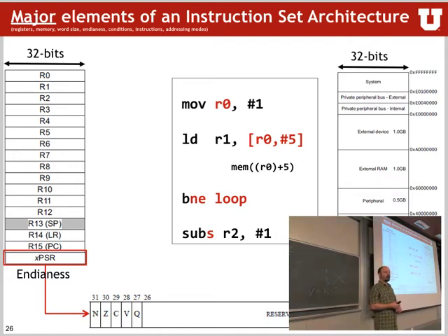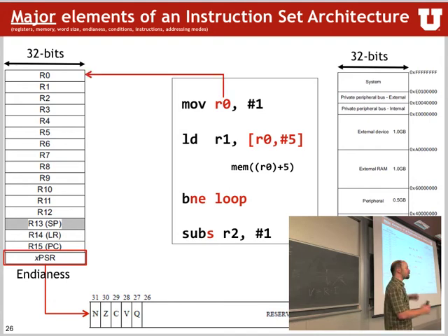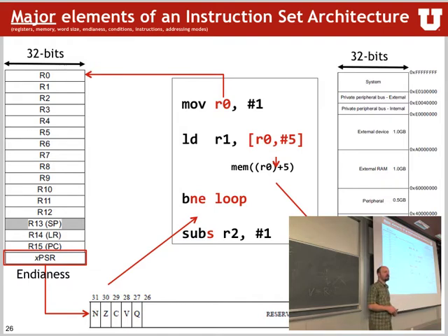We have the language that you're writing. In this case, this is ARM assembly code, where things refer to different major elements. So for example, we have registers that we tell to do things. We have locations in memory, so they are mapped into the memory map to do something over there. We have functions that react on these special register bits that we have down here. We will talk about them in detail. And we have certain labels that refer to something inside our memory map. So for example, what this particular thing here does, this is a move where we want to write 1 into this register.